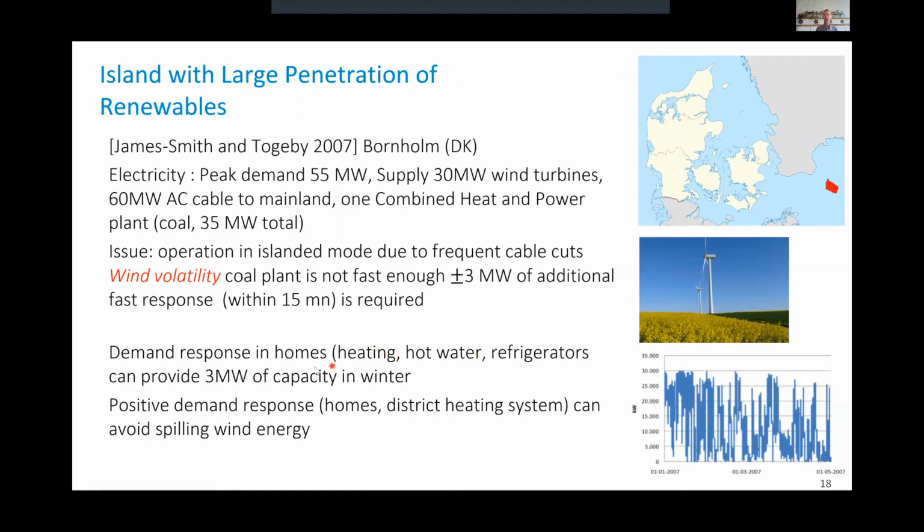One way to avoid this is to also instruct the heaters, the hot waters and the refrigerators, all thermal loads, to anticipate their heating actions. Both have been deployed and are described in this experiment. So this is truly providing a small-scale regulation service where, in fact, all the timescales of primary, secondary, and tertiary are collapsed because the grid is very small.